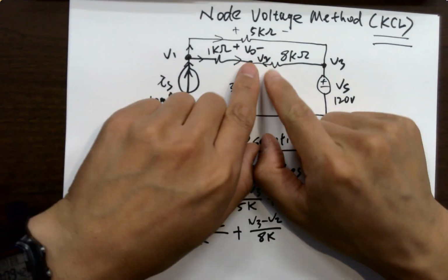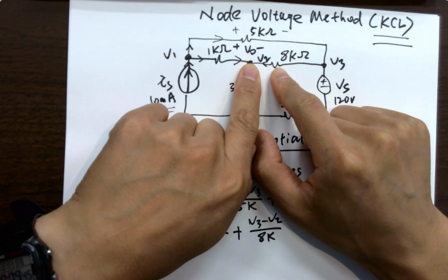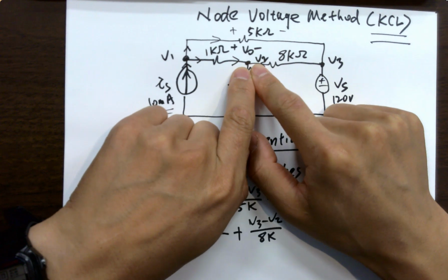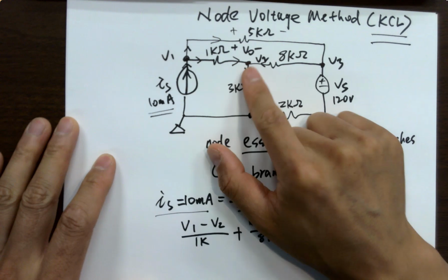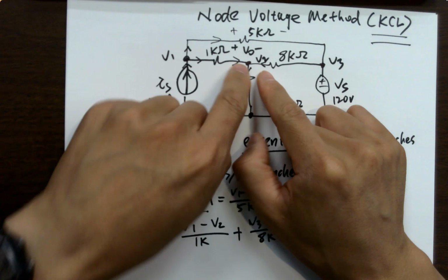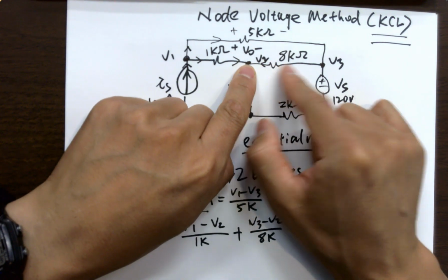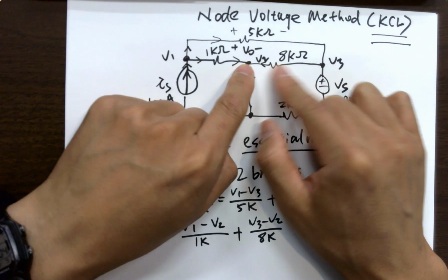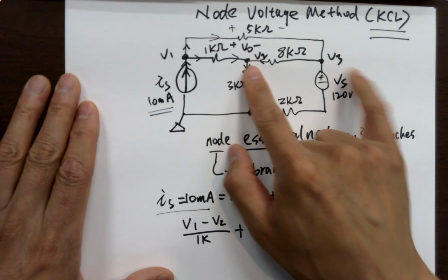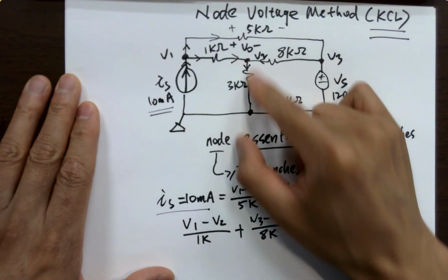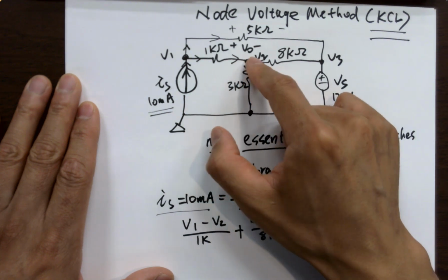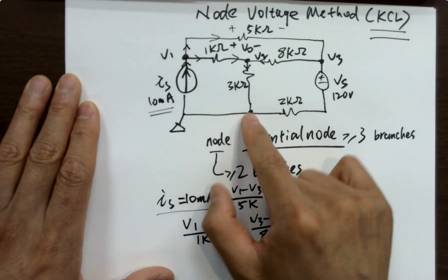So another question, is the voltage across this resistor V2? No. V2 is just the voltage at this node. Sometimes people get confused because I labeled V2 and this V2 becomes the voltage across it. And also I labeled V2, but the voltage here is not a voltage across this one. Why is it different? The voltage across that is the drop from 3 to 2. This is from 2 to 3 and this is from 2 to 0. This is shorted to 0, this is not. That's why V2 is the voltage at that node, but also the voltage across this resistor, because this is grounded.